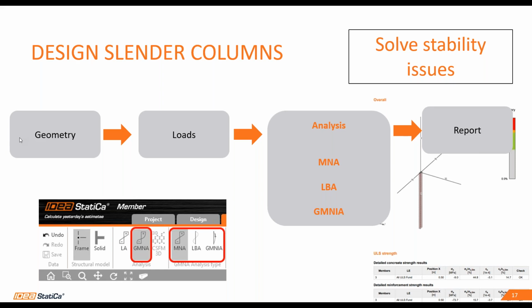After specifying the imperfections, either according to a standard or from experience, you get an imperfect model, which will be calculated with geometrical and material nonlinear analysis with the imperfection. Thanks to this solution, the assessment is done at the level of the stresses and strains, where we make sure not to exceed the design stresses either in the concrete or in the reinforcement. Of course, as standard, a clear report is not to be missed.